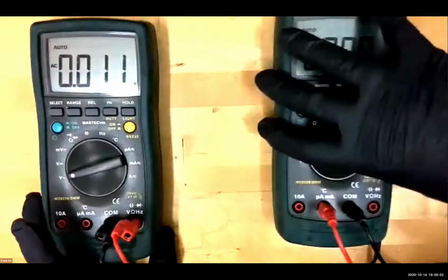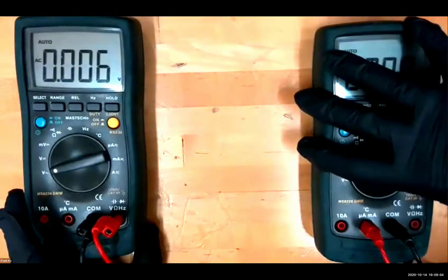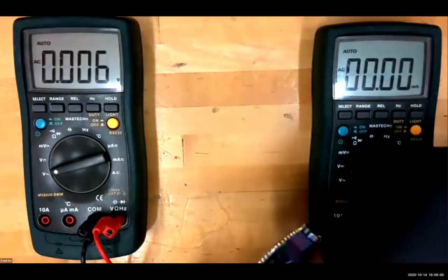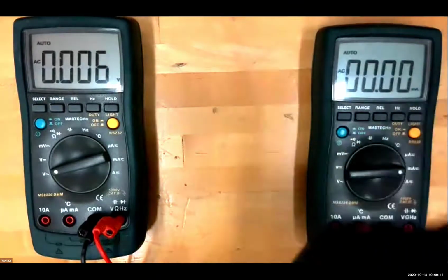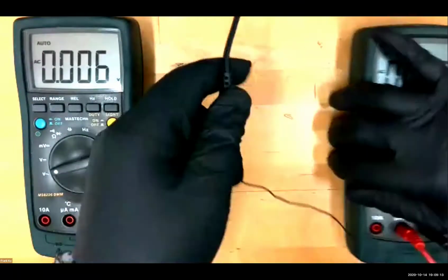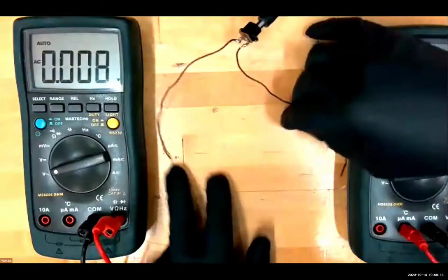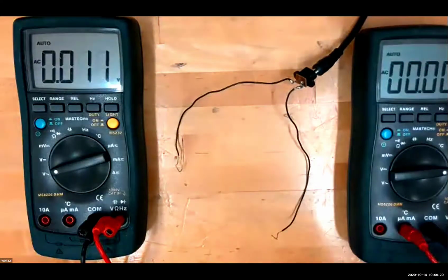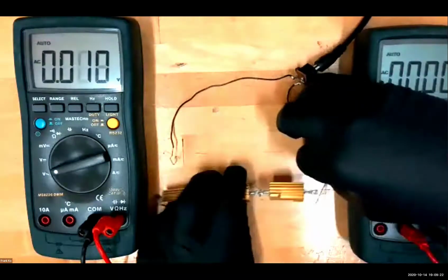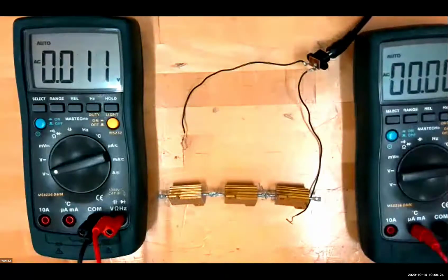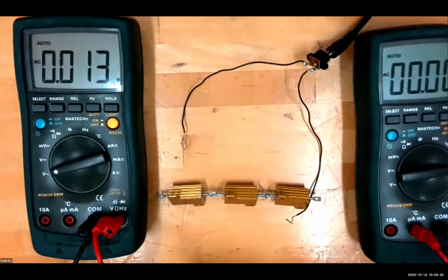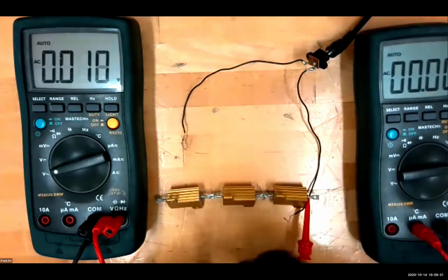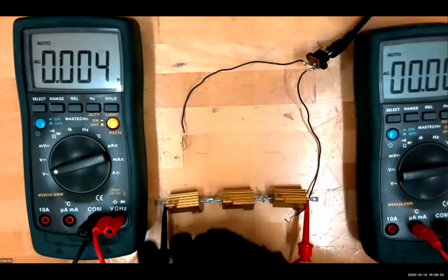Now, that being said, we move these guys apart, and when you go to hook this up, I'm not going to plug in the wall wart now because I don't want anything to heat up. When the wall wart is plugged in, you will have these wires ready to go. So the measurement is done this way. If I'm going to use 1, 2, or 3 resistors, first thing I want to do is hook up my leads for voltage. So I'm going to hook up right across here and here.